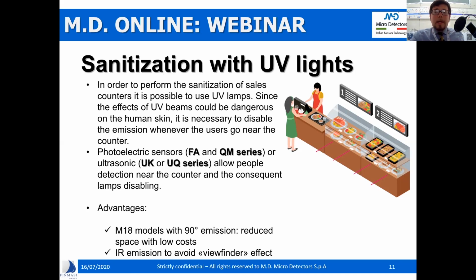So what? It's necessary to stop the emission of these UV lights when a person goes near the refrigerator, near the counter. So we need to detect the presence of a person through the usage of a photoelectric or an ultrasonic sensor.